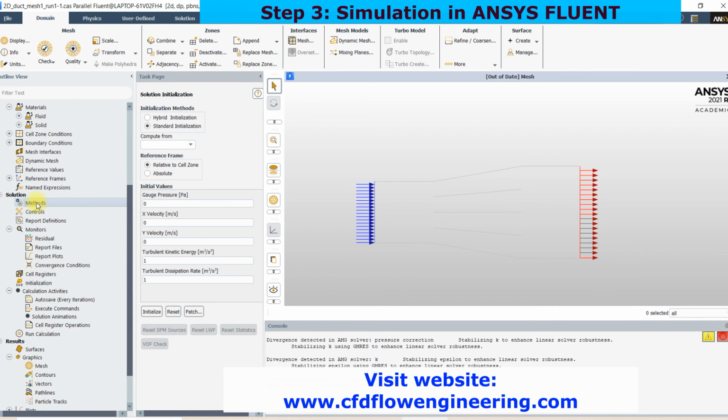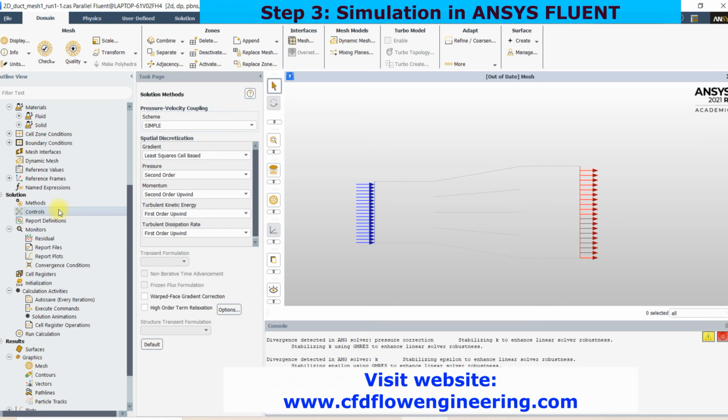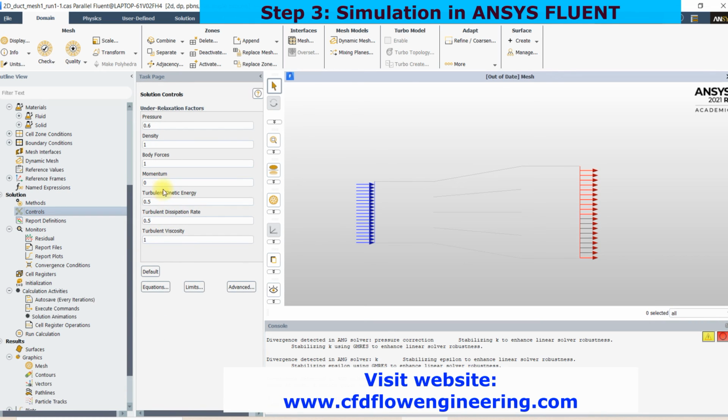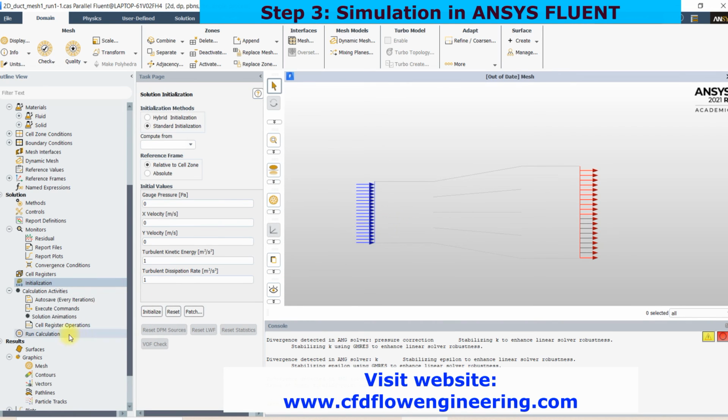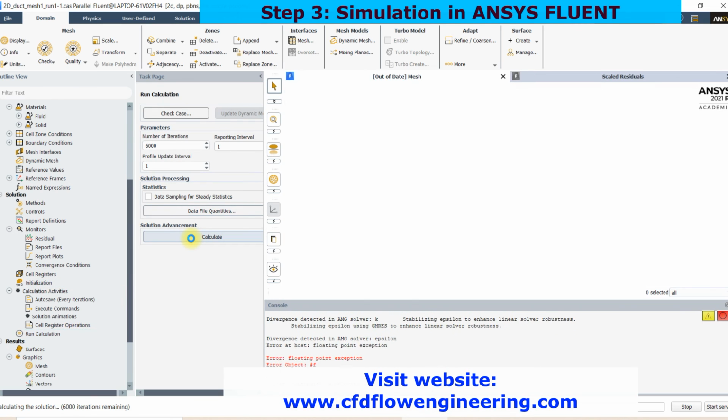We can select the SIMPLE algorithm. The momentum relaxation should be 0.3 or 0.4. That was a mistake. Initialize and then run the simulation.